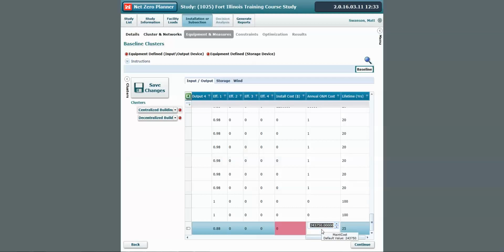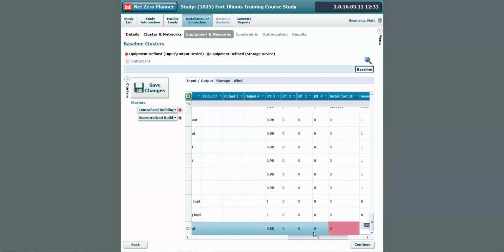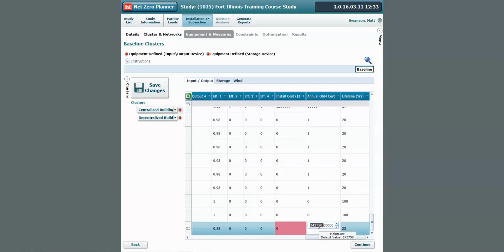Now again, we would need to adjust the O&M costs. Here though, we already have some estimate of the O&M costs for a boiler of that size. If it wasn't that size, you could just scale the O&M cost estimate here. Obviously, the best, most precise way to do this would be to get the data directly from the installation personnel. They may have the information on O&M costs related to that equipment that you'd be able to divide down per piece of equipment. Here, this cost is per each boiler.